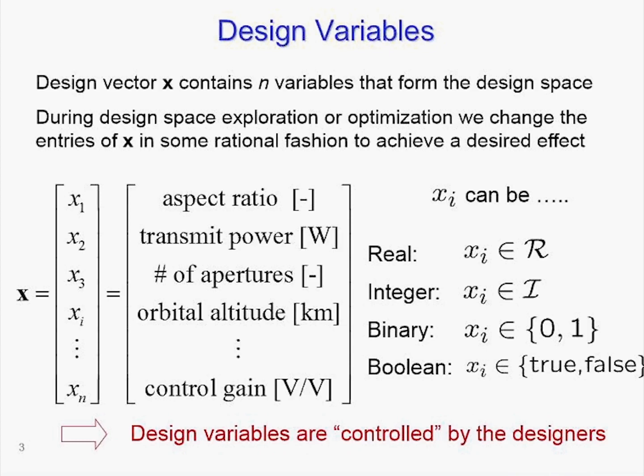Okay, so design variables and objectives. Design variables are what we can change. The objectives are going to be these measures of how good the design, that give us some direction for change. Then we're also going to have constraints. So again, we said constraints are what we cannot violate. So these are going to act as the boundaries of the design space. I said that the design space is defined by those design variables.